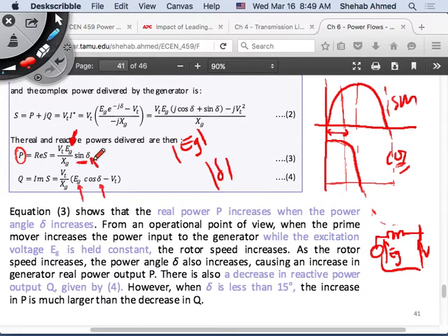But the angle will change. Will it change significantly either? We don't expect one generator to be 100 degrees out of phase with the other generator. When we looked at the solution for the power flow problem, what was the angle at the highest bus? 22 degrees, right? What is the maximum angle? Sine has a maximum value at 90 degrees, right? What happens to the angle after 90 degrees?